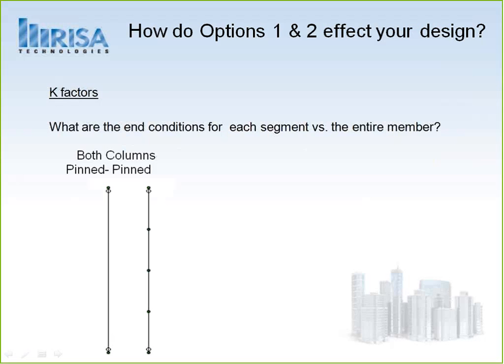And when we do it as the segment method, if we have RISA 3D actually calculate it for us, we're going to see that we get different values popping up along the distance. We're getting 0.8 here because it's a pin fix. We have a fix in this segment, and then fix pin here. So we're going to see different values popping up there.